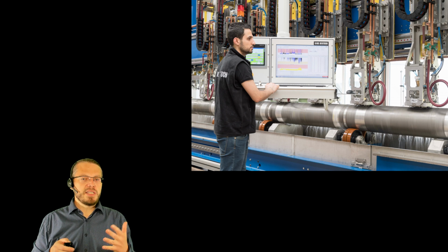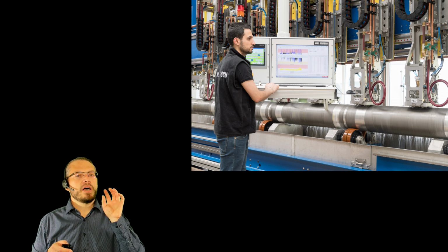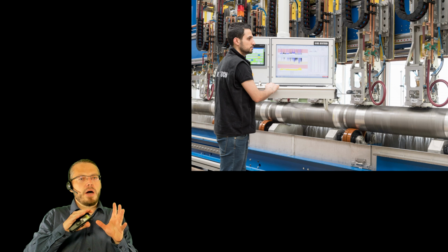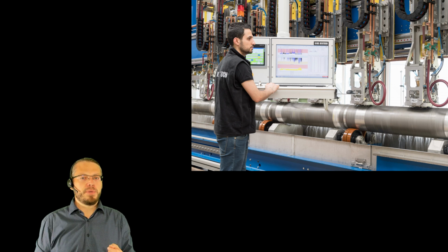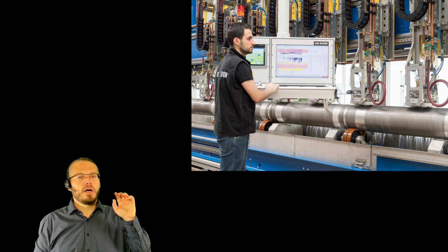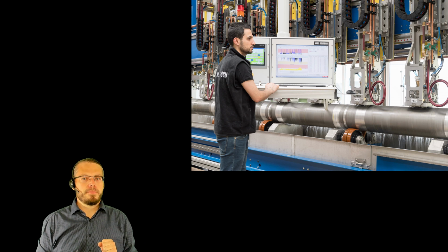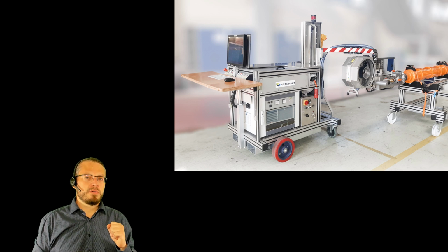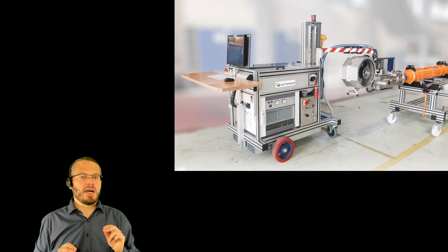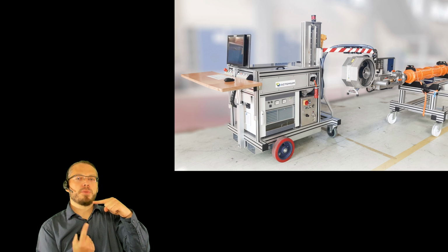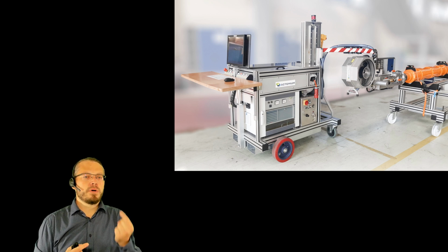Now, what we can also see in this example, we are using water as a coupling, or in some cases also oil, and you can see how the water is here in the back of that component. So we are still using a contact inspection. We can also inspect such railway shafts, so railway axles, from the inside with such a system. We have a mechanic which goes inside, presses our probes from the inside against that shaft, and then we do the inspection from the inside to the outside.